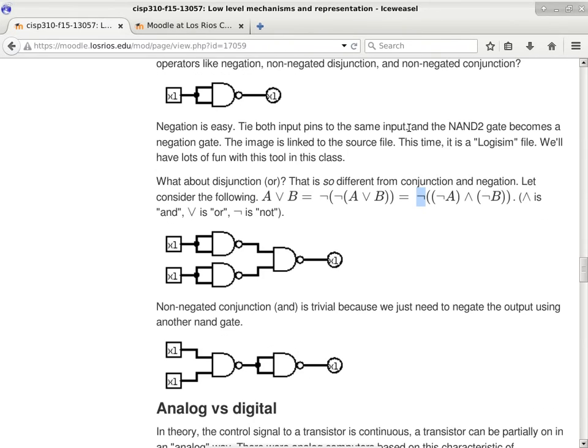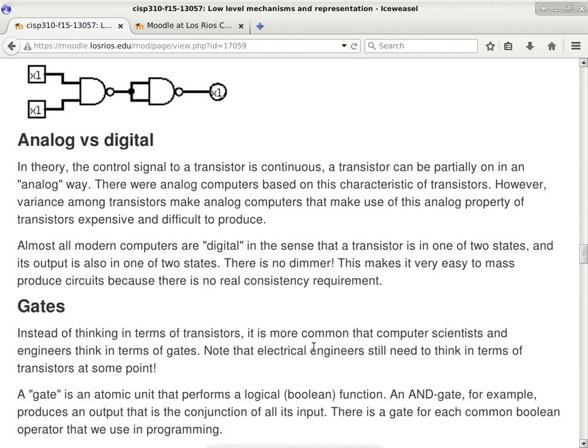It is easier, exactly, because if you want to make an analog computer, the pitfall of an analog computer is you have to select your components very carefully, because the transistors all have to respond exactly the same way. If I apply 50% of the full voltage, I need the transistors to turn on to the same degree. That is not easy to do. Matching transistors so that their behavior, not at the extremes but in between, is identical, that's not easy to do. And that's partially why stereo equipment or power stereo equipment is expensive, because they have to match the characteristics